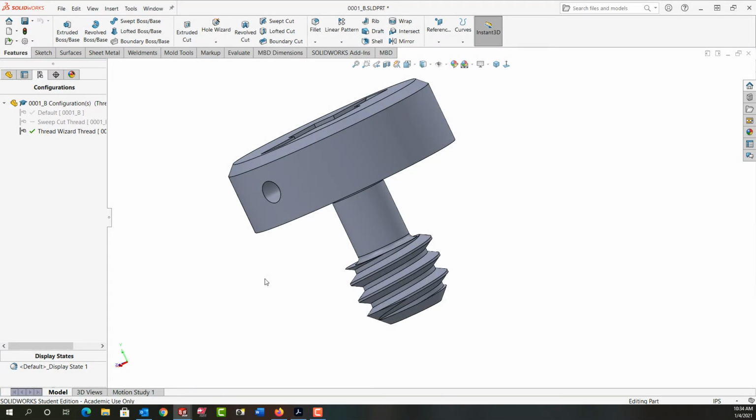In this video, I want to demonstrate how to use the Thread Wizard to model a thread as shown here. Before we do that, we should discuss why we would bother with this. Well, one of the few reasons to bother with actually modeling a thread is we're going to 3D print the part on a rapid prototype machine, and we need the physical thread to check that it's going to work, or a boss or customer has asked for it.